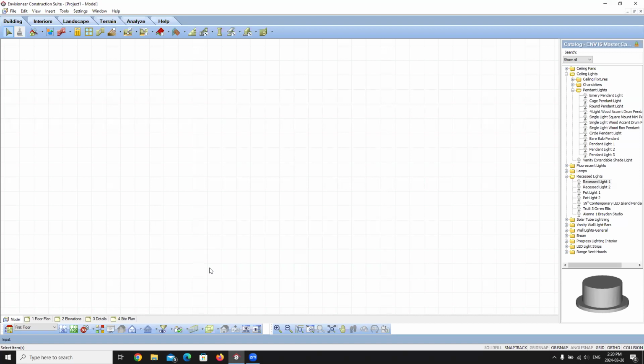So let's draw some walls to exact dimensions. When you know the exact dimensions that you want your perimeter walls to have, you can use the Walls by Baseline tool. This option allows you to type in a precise length for each wall. As you draw your wall segments, a self-closing diagram is going to be formed. When you have finished specifying your wall lengths, you are then prompted to specify an offset method for the walls relative to the baseline that you have just drawn. You can offset them from the outer face of the veneer, from the outer face of the wall core or stud, or from the inner face of the wall.